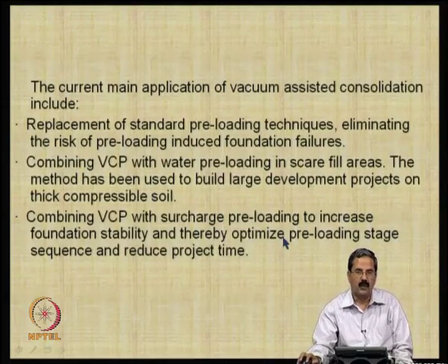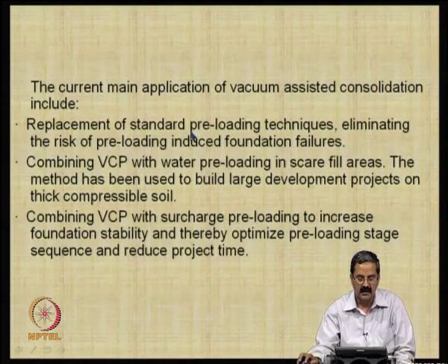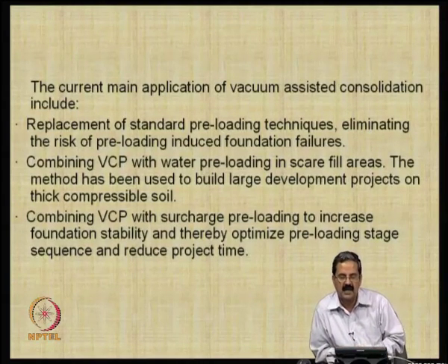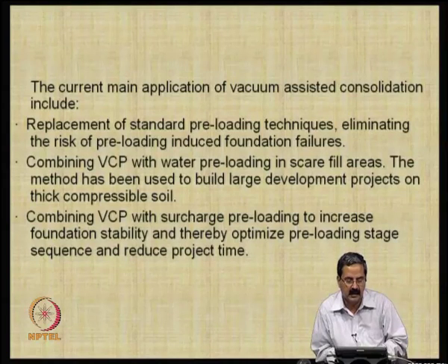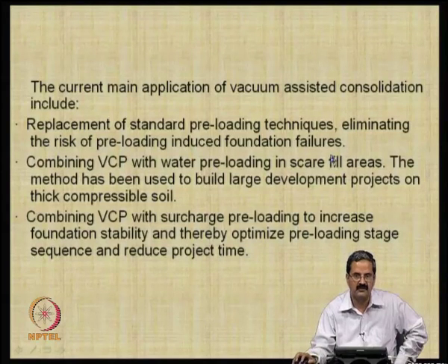What we are trying to see here is that the current main applications of vacuum assisted consolidation include replacement of standard preloading techniques. As I said, standard preloading means adding a lot of sandbags and other material. The problem is, as I just mentioned, that it eliminates the risk of preloading induced foundation failures.